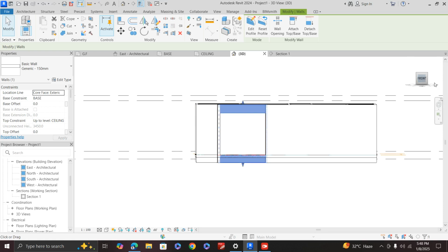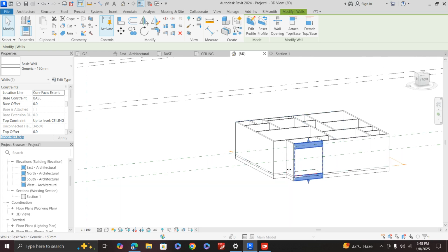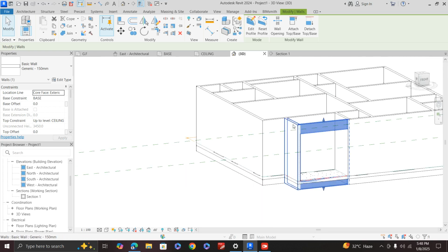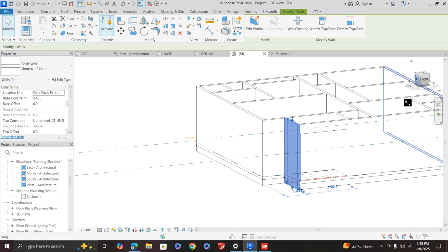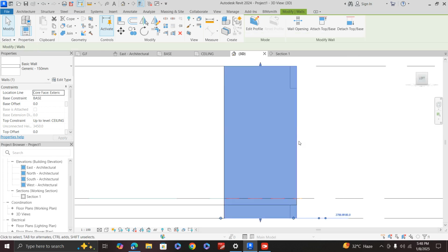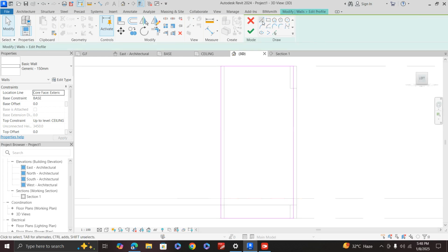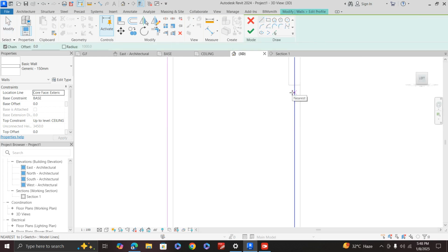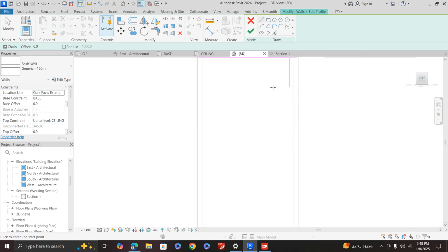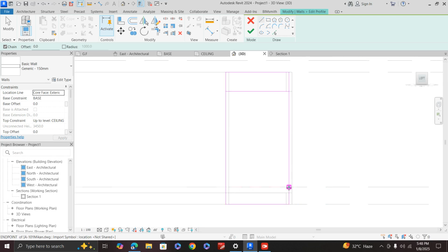Then come back to this view and then click on this other wall, then use the left view, then do the same process. So in this case we do not need to offset because you can see the outline of the front wall already done previously. So we can trace from that line down to this one too, and then we can trace here as well.